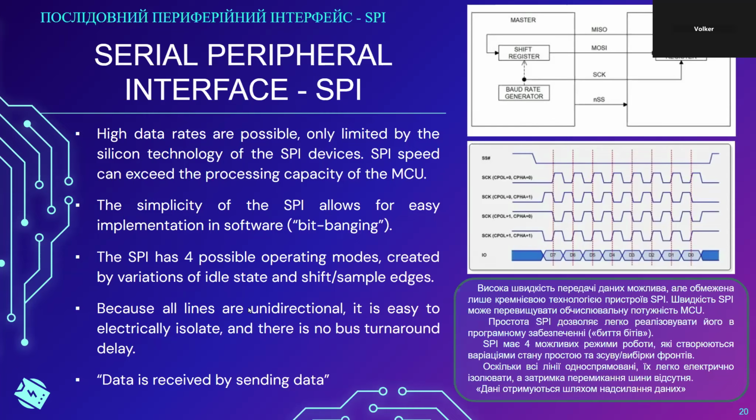It is, of course, still vastly inferior to an actual SPI interface module that is on the microcontroller. But at the same time, if 4 port pins is all that you have available to connect to an SPI device, you can do this. So because of its simplicity, it is possible to implement SPI in software.